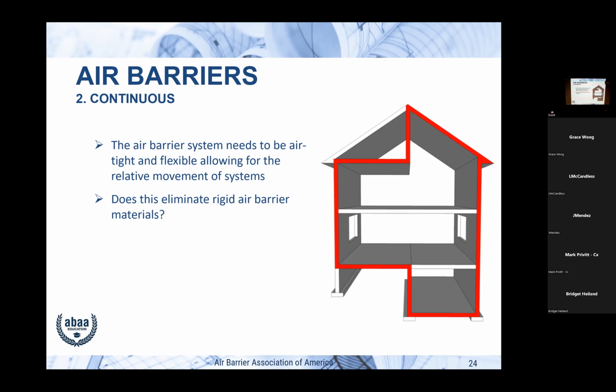And this is very basic, but you're going to get into some of the pictures that Andrew showed you. That could be very tortuous. And the air barrier doesn't have to be a nice straight line through the whole building. It can move all over the place. You've got to watch, though, again, where you're placing the air barrier versus thermal insulation and so forth. So make sure you understand where you want to stop the air leakage.